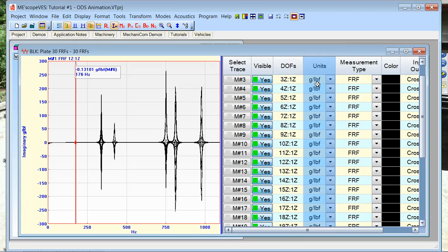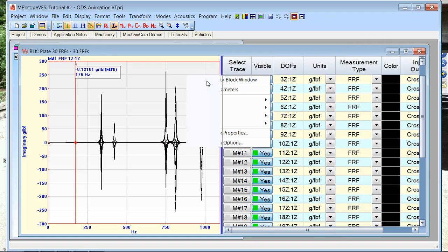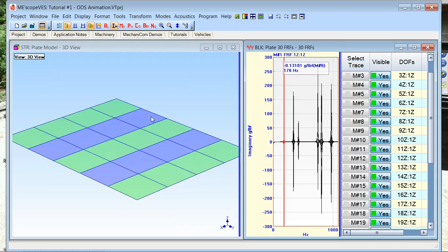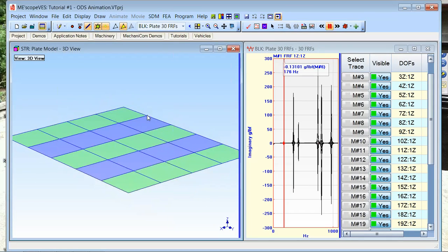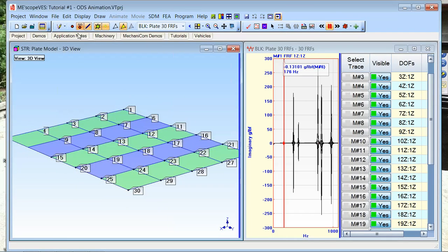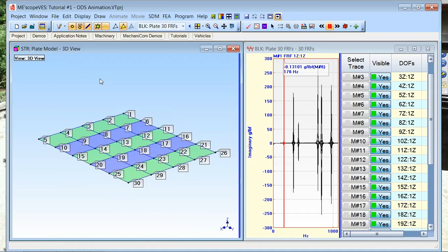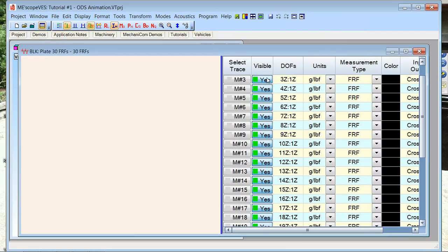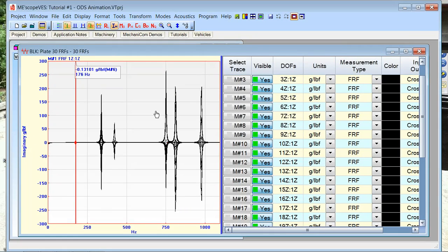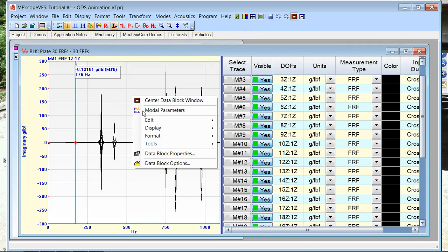All these terms apply to the resonant behavior of the structure. So normally when we're looking at vibration data, we want to know, are there resonances being excited? This type of measurement will isolate those as peaks in the data. That's why we make this type of measurement. An FRF always has units of response divided by force. So it's either going to be acceleration, velocity, or displacement divided by force.